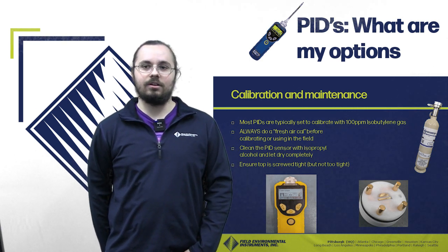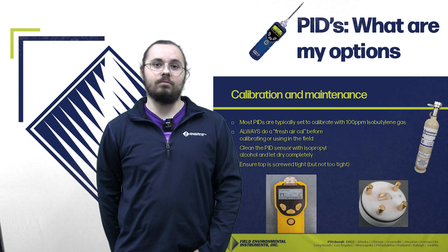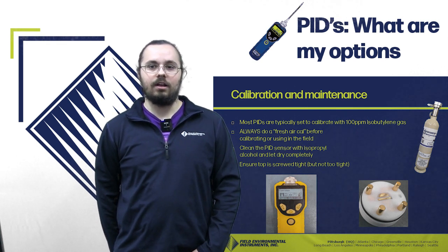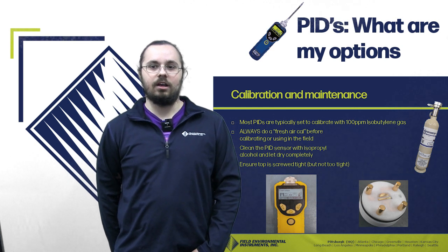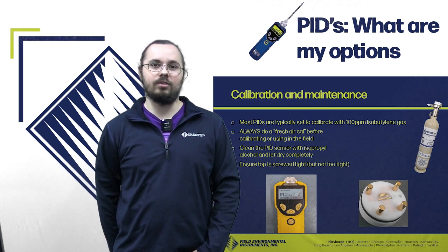Like we said earlier, most PIDs are typically set to calibrate with a 100 ppm isobutylene gas. Remember, it's important to always do a fresh air calibration before calibrating your unit or using it in the field. If your PID ever gets dirty from those contaminants we mentioned, it's best to just clean it with isopropyl alcohol and make sure it's completely dry before you put it back in the unit.